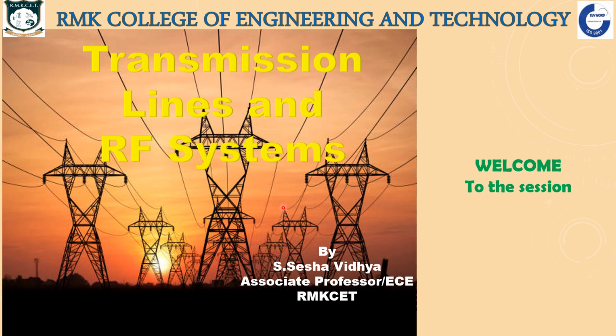So the condition, if there should be neither frequency distortion nor phase distortion, is that LG should be equal to RC. LG, that is inductance and conductance, should be equal to R into C. If any transmission line satisfies that condition, then we can call it distortionless. But practically speaking, LG equal to RC is not possible in a practical case.